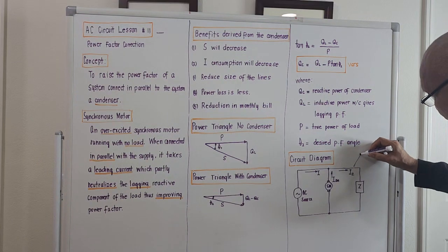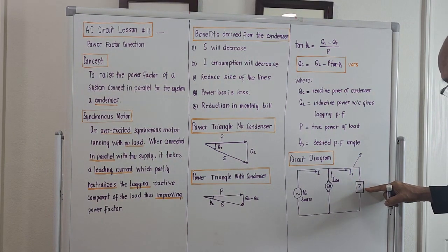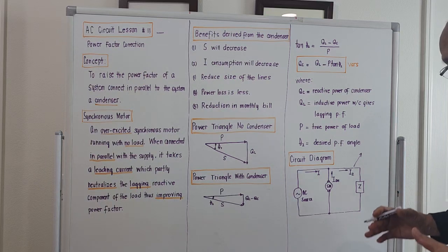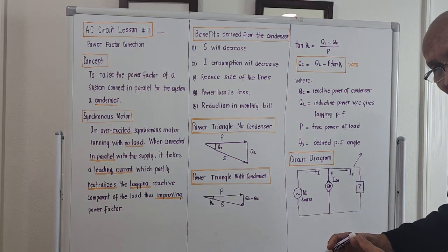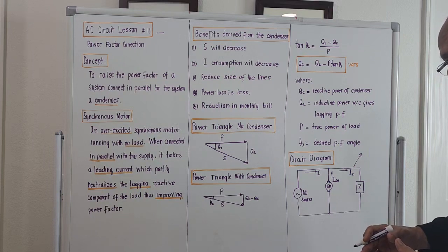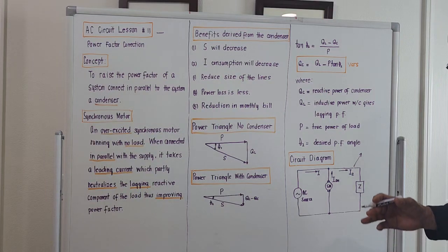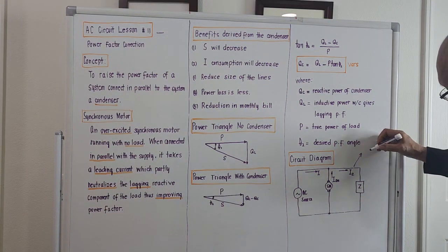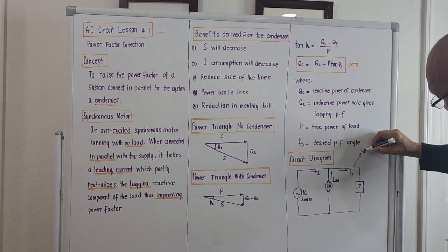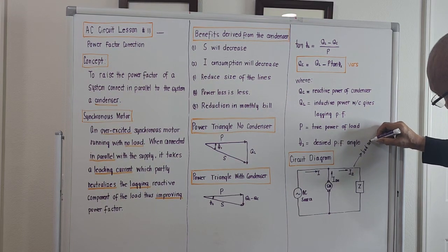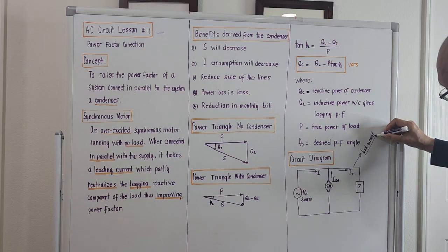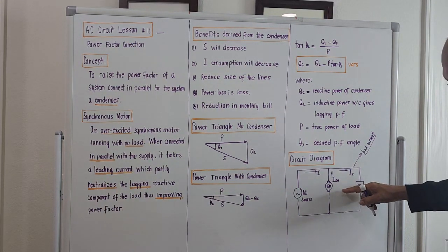The current being consumed by the single equivalent load is a bad current because it comprises motor load currents. It is not so effective in apparent power consumption. So this bad current will be contradicted by the good current of the synchronous condenser.